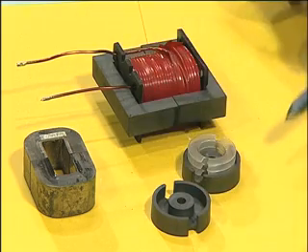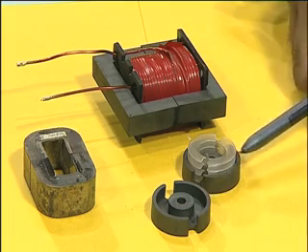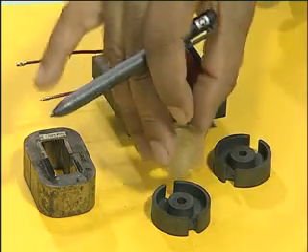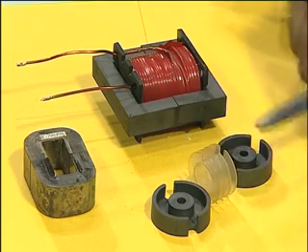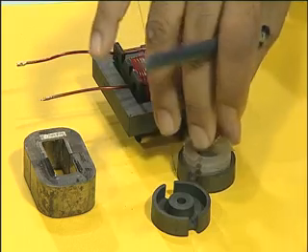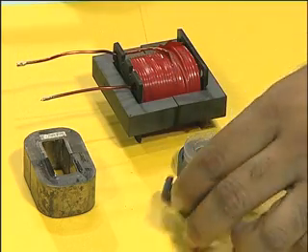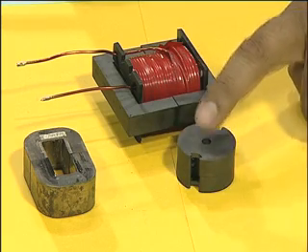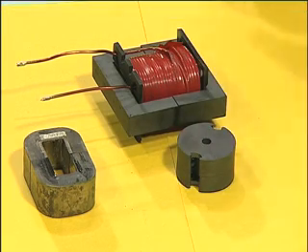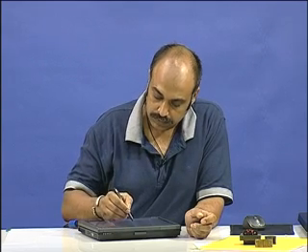This has two halves, you have the bobbin here, on the bobbin is wound the copper wire and then it is placed within the pot core like that, and then you enclose the bobbin. So, you have the core enclosing the bobbin and flux flows through the coils. Okay. So, this is how the inductor has to be manufactured, and it is basically dependent upon the following equation.